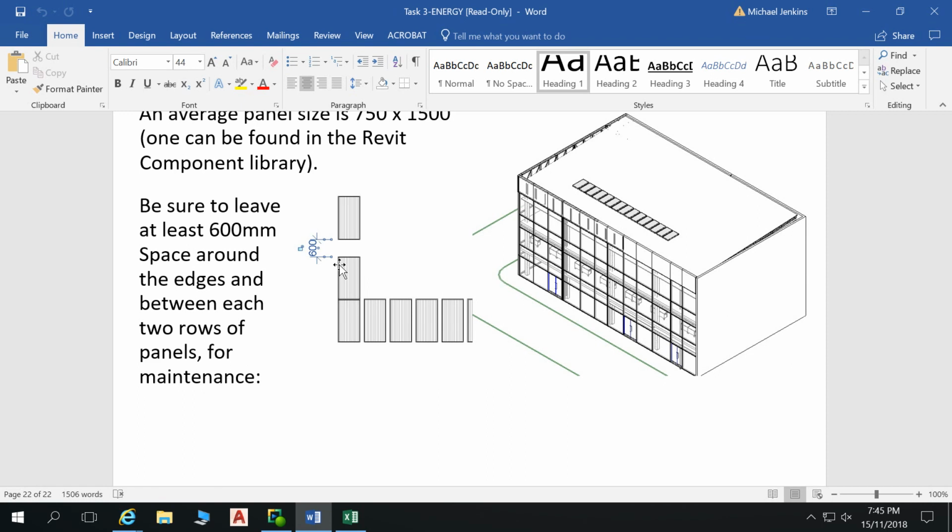So you set the rails out, and then you drop your panels in and lock them into those rails. That's fairly simple. But then you've got wires underneath your panels. You've got to bundle up and pick up your wires, use cable ties, and then you join all those wires together. So you have your panels tilted up, you join them up together and drop them down. For doing that, you need to have space at the end of your panels for when you're working.